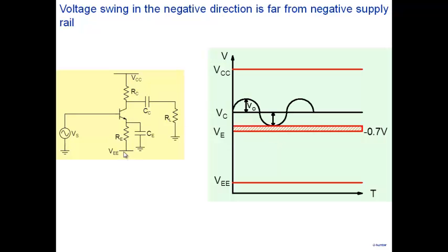If by adding a negative -5 here, my swing could have also gone to a large negative value, it would have been fine. But I can't increase the swing, because if you look at this particular circuit, this is 0 in DC, and so this is -0.7. So the emitter end is fixed at -0.7.